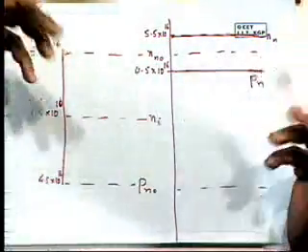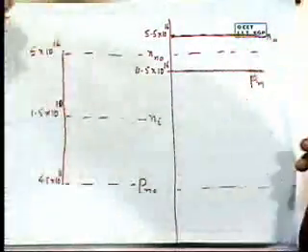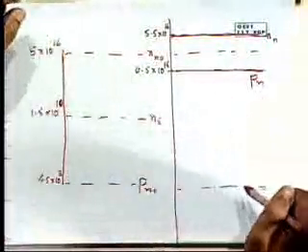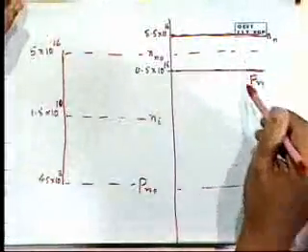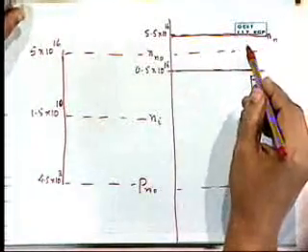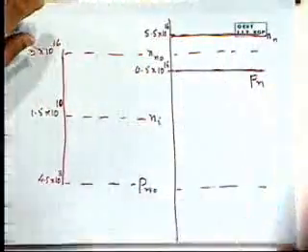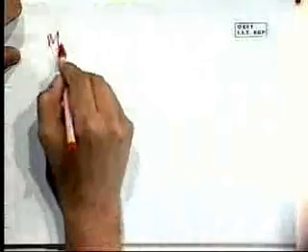Now when it comes back into equilibrium, when we stop the light, what's going to happen? These things have to recombine to establish these two equilibrium values again. So all these holes have to go somewhere. This extra number of holes that were created are going to recombine with the extra electrons that were created. But it's going to take some time, and in that context I introduced the idea of minority carrier lifetime.